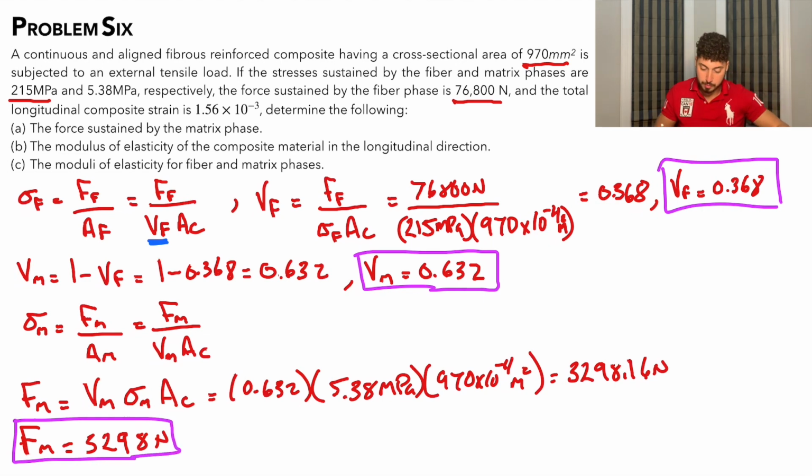And again, I want to remind everybody to change all their megapascals to pascals, all their millimeters to meters, and all of their forces to newtons, and this way all of the units will come out in the desired units that you're looking for. So now let's move on to part B.